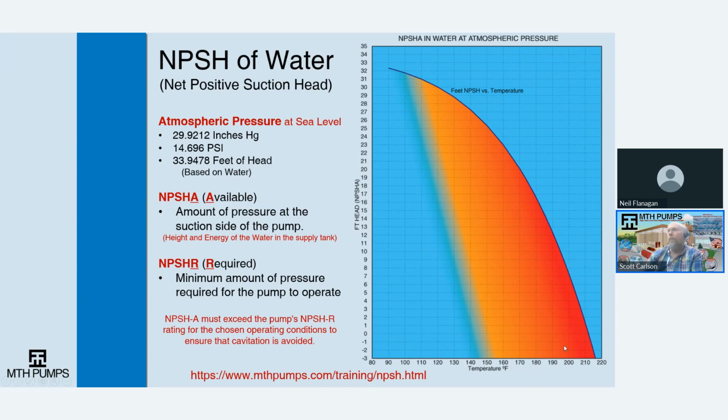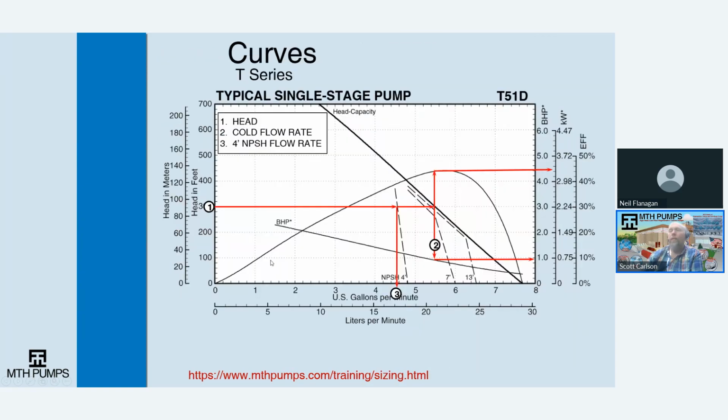With a centrifugal pump, because the fluid goes into the center of the impeller, when water starts to boil, it forms bubbles. Those bubbles take up the space of where water is supposed to flow, and water will completely stop flowing in a centrifugal pump when the NPSH is too great.